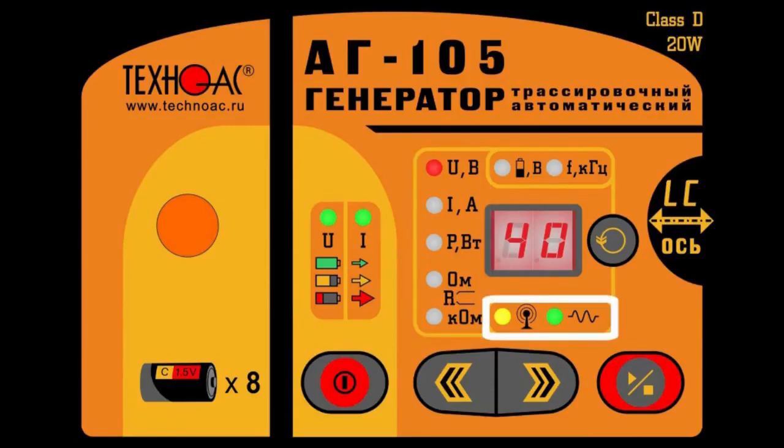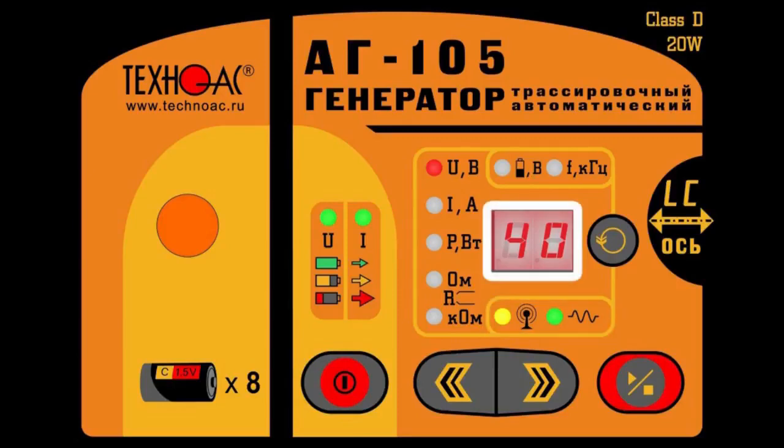Indication of modes area: antenna mode if enabled, modulation activation and type of generated signal. The numeric field indicates the following parameters: LC, built-in antenna activated; AN, external antenna activated; CO, continuous signal of transmission; PU, pulse signal of transmission; 2F, simultaneous transmission of two frequencies.